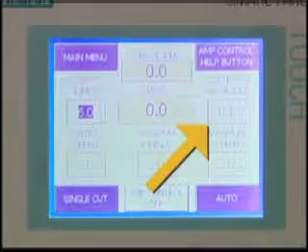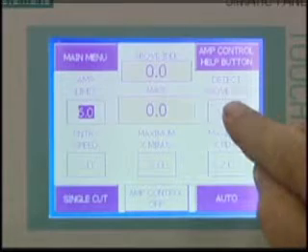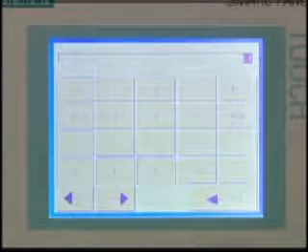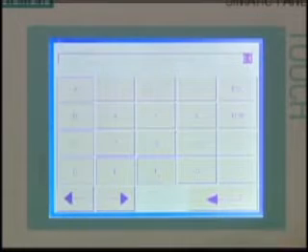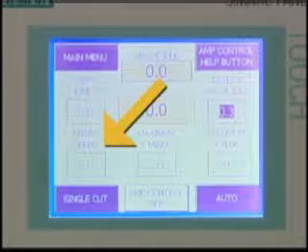The Detect Above Idle setting determines at what point the machine will engage amp control. This setting should be between 0.1 and 0.5, depending on the depth of the cut. Thin material or shallow cuts require a lower amp setting, such as 0.1, but 0.3 is a good setting for most work. Enter the x-axis entry speed.